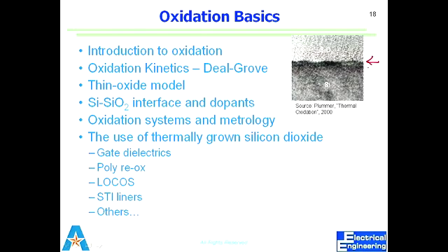Dry oxide is used on the gate; it's slow to grow. Most of the other oxides will be wet oxides. If it's field oxide, there is too much area to grow. We want it fast because the electrical quality doesn't matter there.